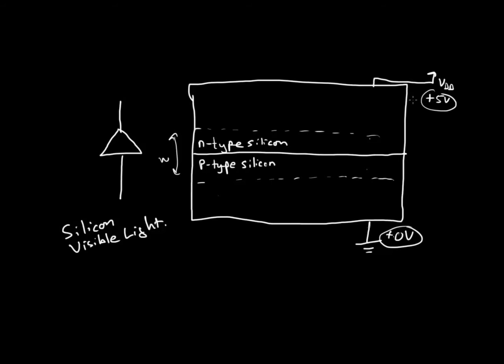When you apply that potential, that depletion region will actually grow. And let's assume that the n-type silicon, the depletion region, has grown all the way to the surface of the silicon. And let's assume that for the p-type silicon. That's in fact usually not the case, by the way, that photodiodes and image sensors are manufactured. But let's assume that we've fully depleted this volume of silicon. What happens when this volume of silicon is fully depleted and we illuminate it with visible light?